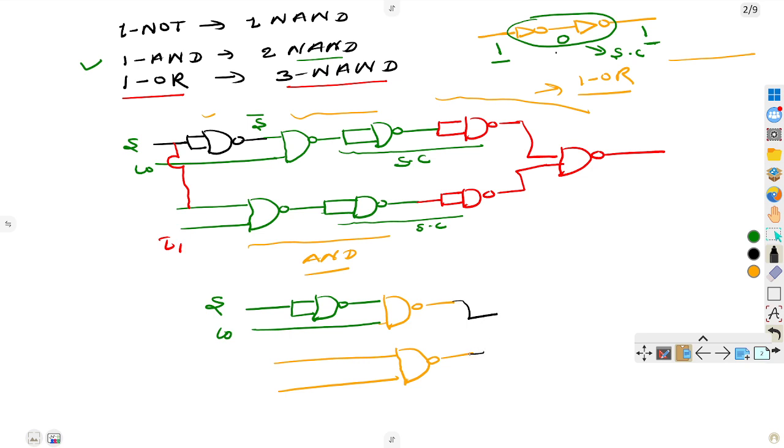So how many NAND gates are needed? Only 4 NAND gates. Because of that, we need to convert it to minimize. What is the minimum number of two input NAND gates required? Okay, this is the important thing. So this is the S, and this is the I1. So you can say this is the S bar. No need to write this, but no problem, if I write, no issue. So this thing and I1, and this is the NAND gate.